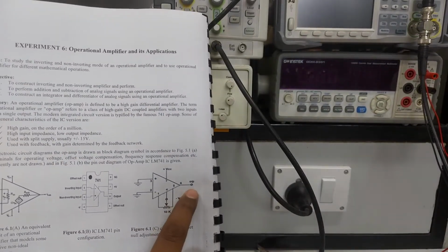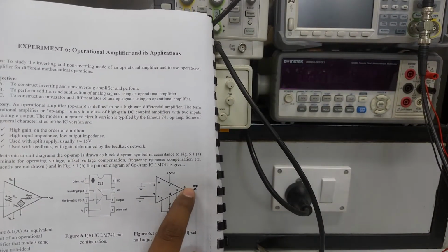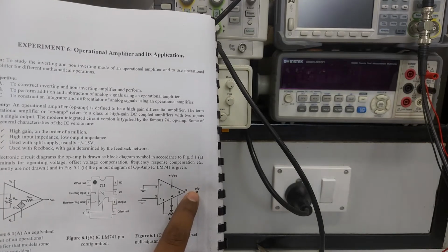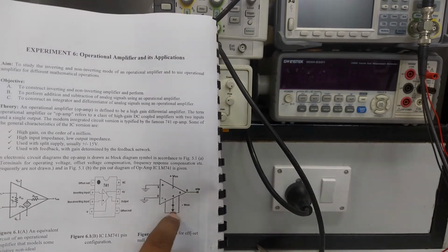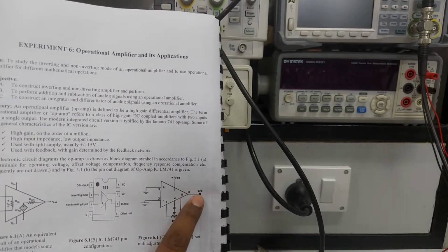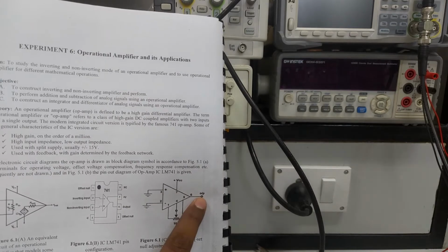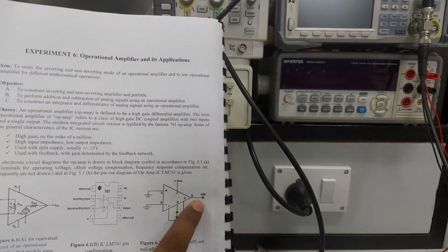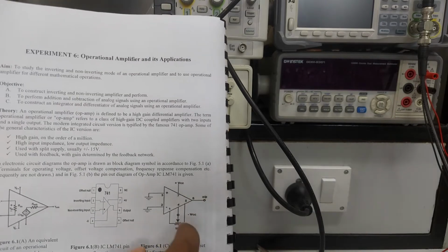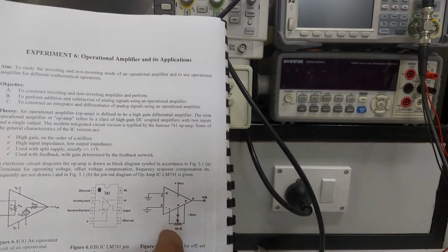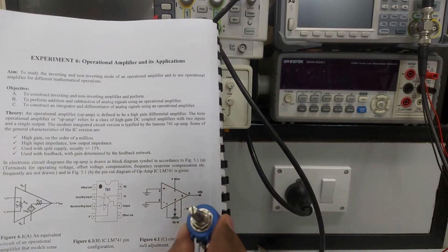Now I'll connect the output with the multimeter to see the output DC voltage, so that by adjusting the potentiometer we can minimize the output voltage. Whatever the mismatching at the input, we should minimize it by adjusting the bias, plus minus VCC, by adjusting this potentiometer.